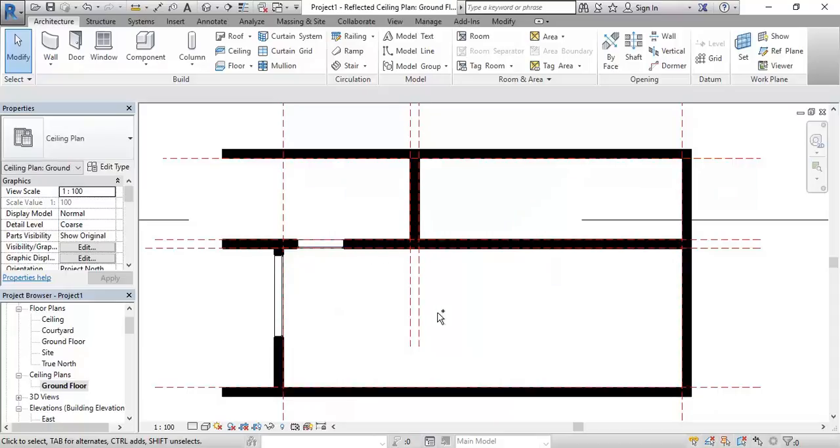That's right, we're not seeing the doors in the ceiling plan. We've got wall above the door, and so this means if we can't see the door, the cut plane must be much higher than it is in the floor plan. And that's normal actually, so ceiling plans often will have the cut plane up at either 2 metres or sometimes above the door head even. I try to keep them under the door head, but some people don't like to see the doors in the ceiling plan and they'll have it up at about 2300.